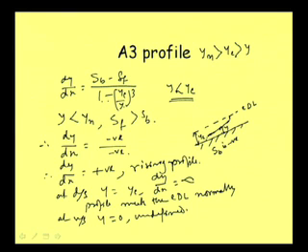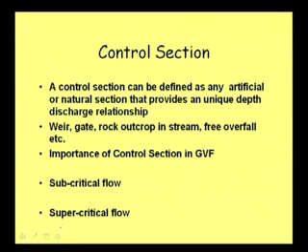Well, now with this understanding of the characteristics of gradually varied flow profiles, let us discuss another topic which is very much related to the computation of gradually varied flow profiles, that is called control section. Now, control section in general is also important for some other work related to hydraulic engineering.